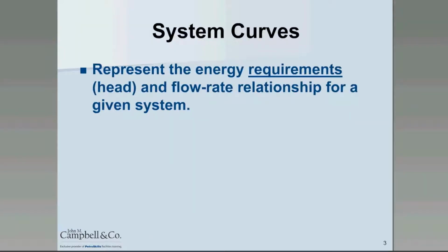Okay, so when we talk about system curves, I know that this is probably straightforward for a lot of people, that they're like, yep, we know what a system curve is. But when we talk about a system curve, think of it as a representation of the energy requirements to induce a specific flow through the pumping network.